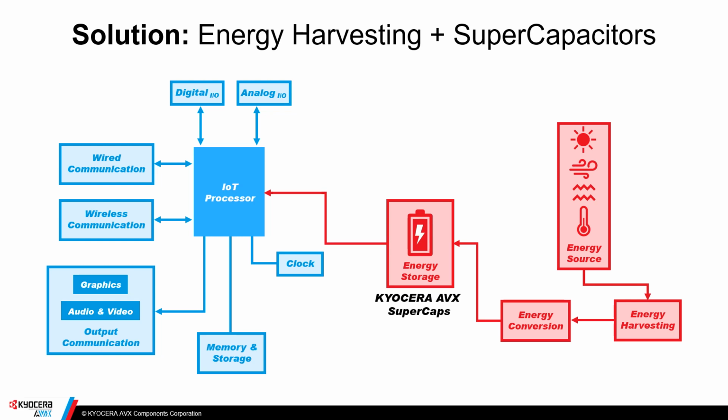It might be solar, wind, micro hydro, TEG, piezoelectric, something along those lines. That energy harvesting is going to occur. It's going to go into some form of a PMIC to charge up the supercap, and then we take that power from the supercap and power the IoT module.